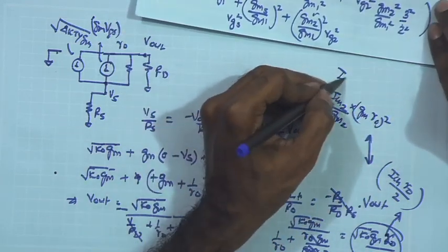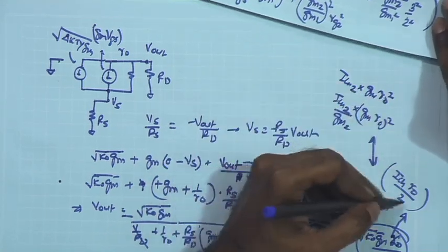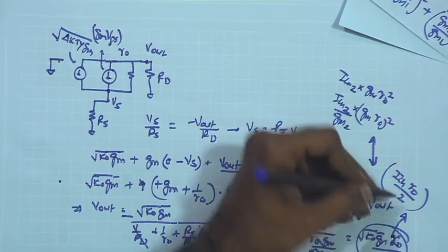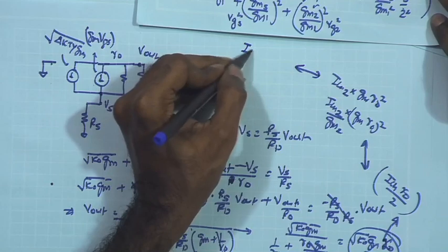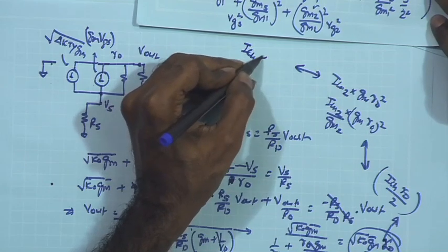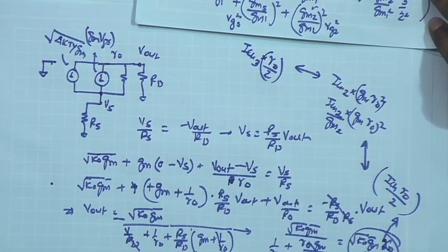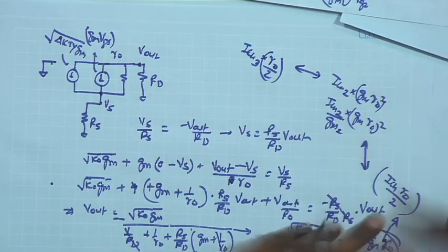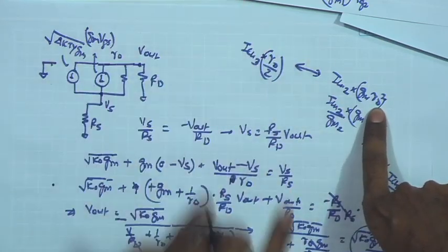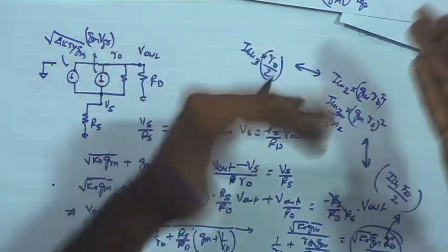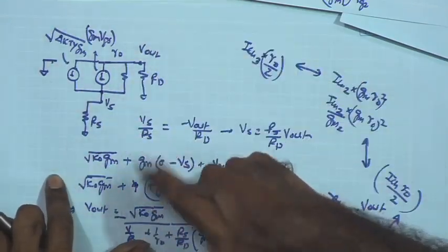So basically I have ICH2 getting Gm times Rho square, whereas the ICH of the Cascode device is just having a factor ICH times Rho by 2. So here you are having Rho by 2 and here you are having Gm Rho times Rho, right. So from a magnitude point of view, once again the same conclusion, that the overall noise voltage at the output because of the Cascode device is Gm Rho times smaller as compared to the devices which are connected to the VDD and ground, that is the M2 and M5.